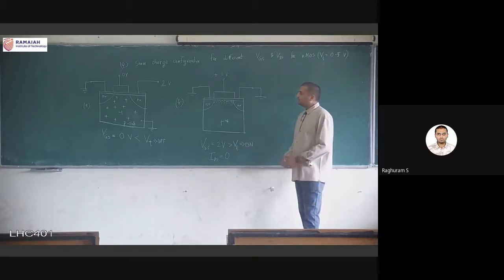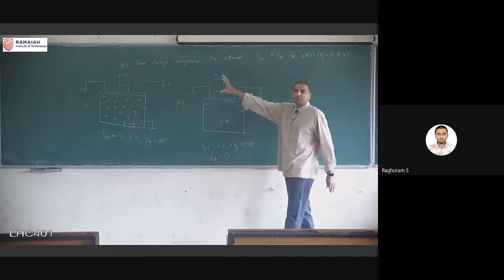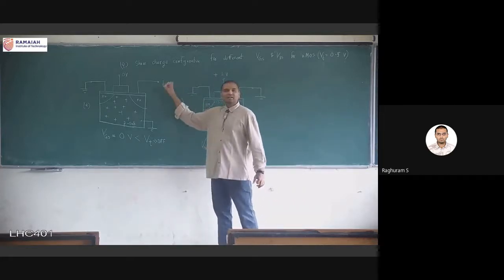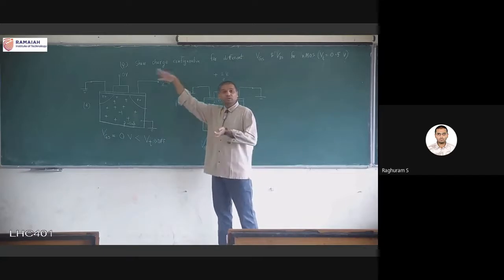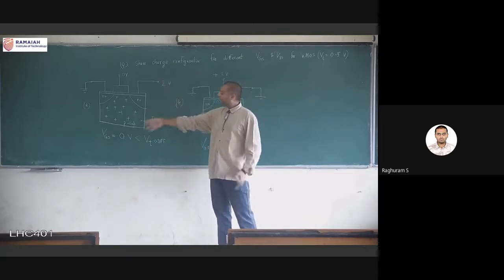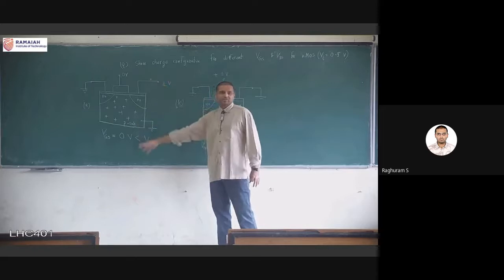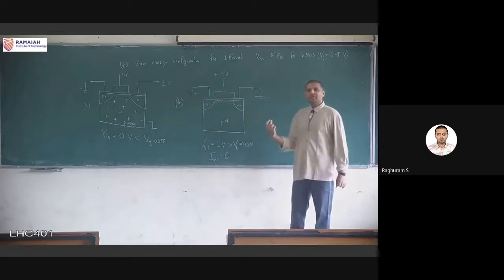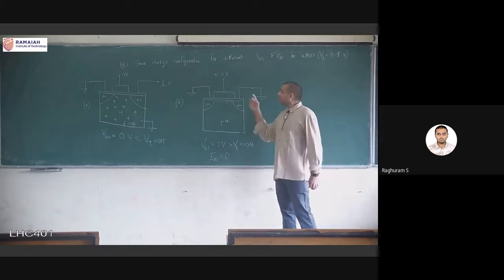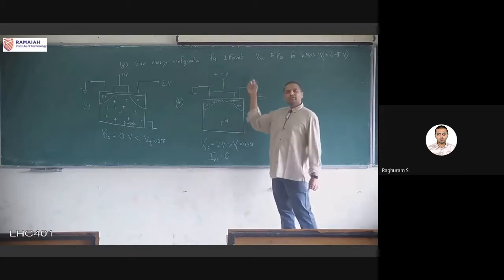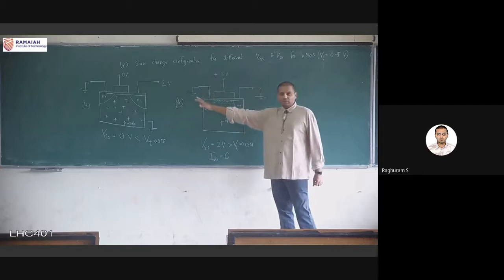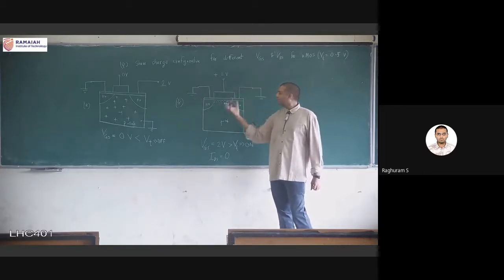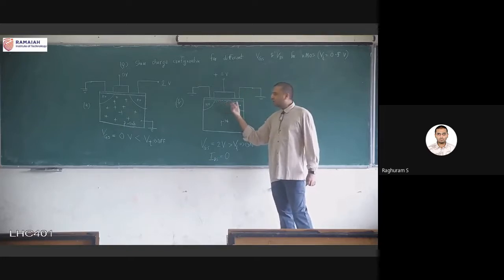Now what we will do is maintain the transistor off. There is nothing else to see. Off means it is off. I can keep changing this VDS. 2 volts can go to 0 volts, 2 volts can go to 5 volts. It can go to any value. The current will still be 0 in this case. So there's nothing much to see here. Here we will see a few different things. When the transistor is on, we will try to slowly increase this side. One side will be at ground only. The other side we will slowly increase the VDS value and see what happens to this charge configuration.